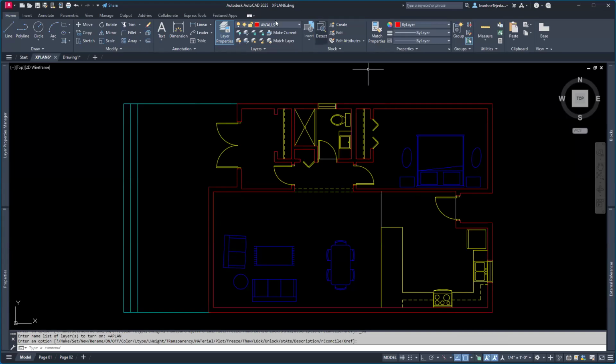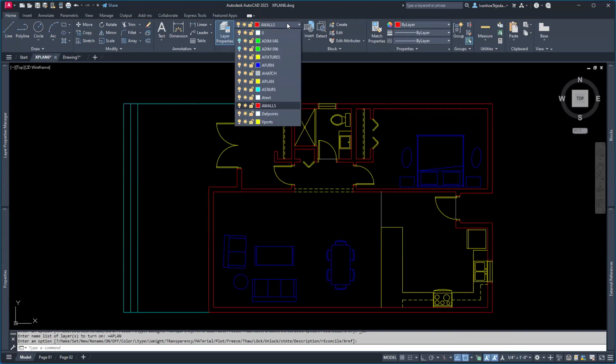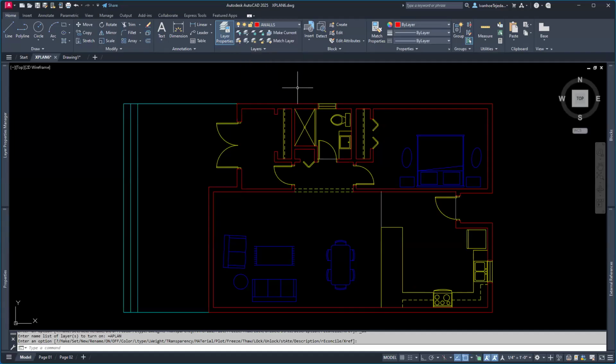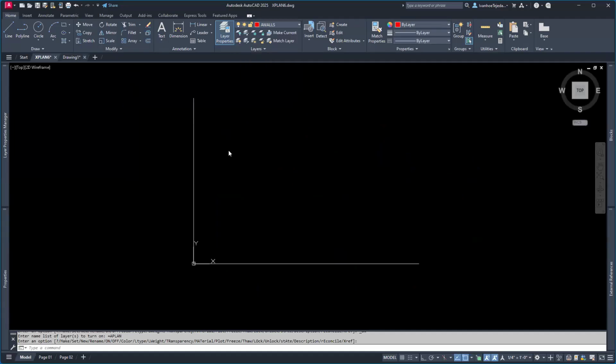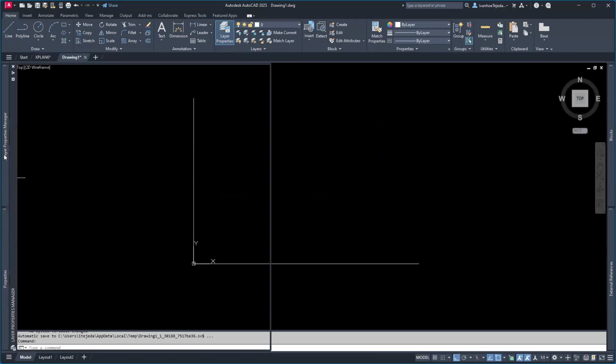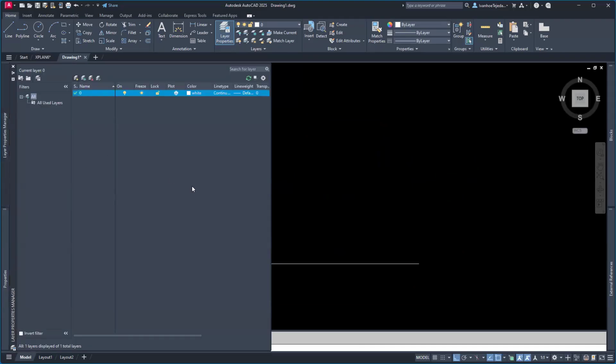So those two layers, the A walls, architectural walls, and yes, the A stands for architecture, and then our architectural plan information. And if you want to call this wall, that's fine. It doesn't have to be plural. So A wall, A plan. So I'll go back over here, and I'll go to my layer properties manager, click here.